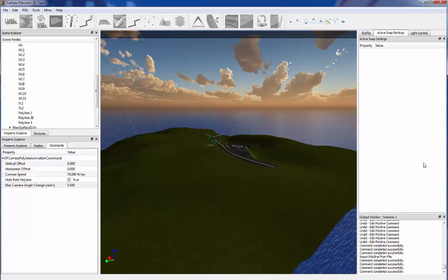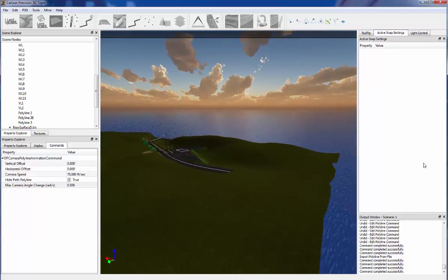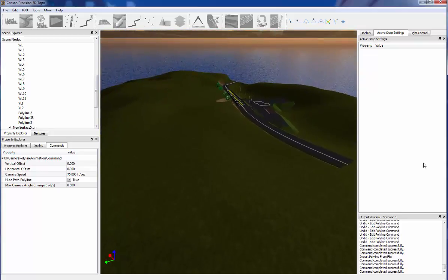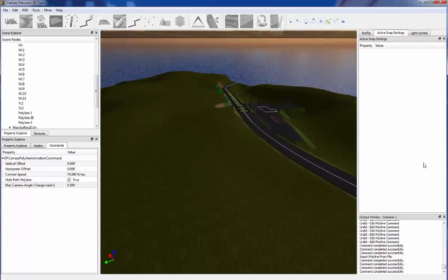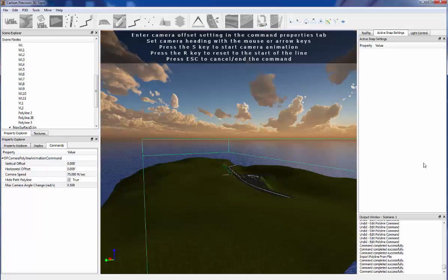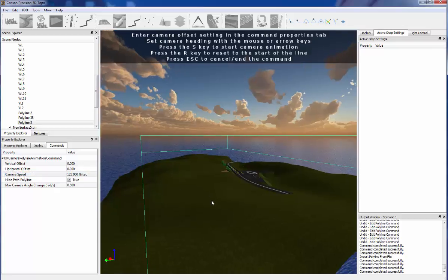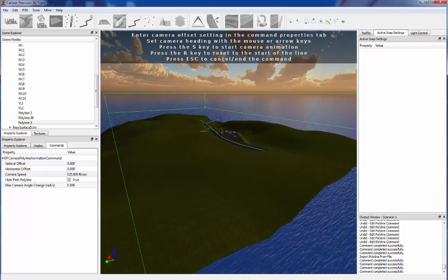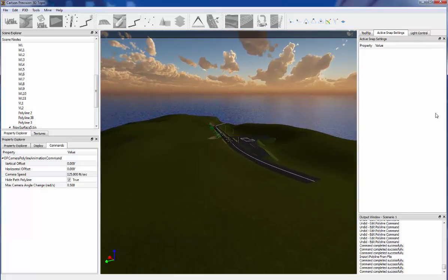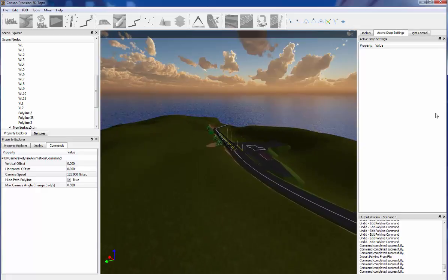And I'm going to press S. And so basically now you notice that the camera is moving a bit quicker. We can pan down and around, and in this case, I think the speed is probably just a little bit too slow. So what I'm going to do is bump that up to 125, pan down just a smidge, re-hit the S key, and that's a little bit better.